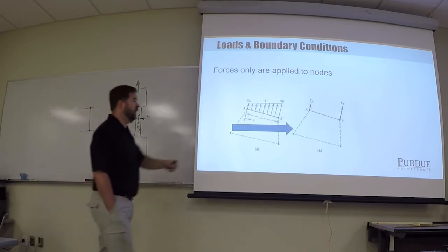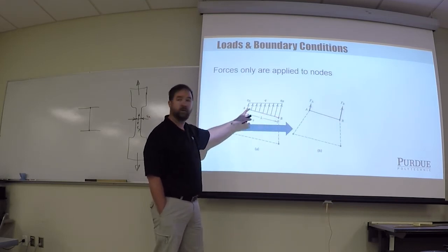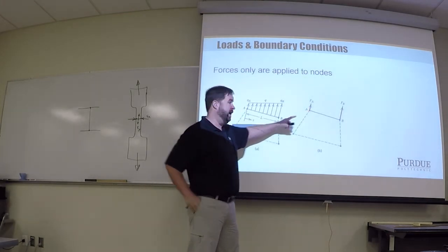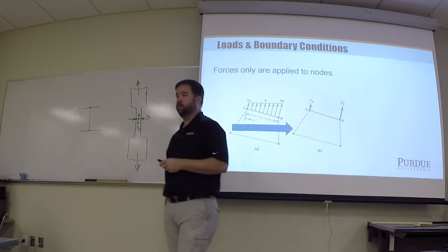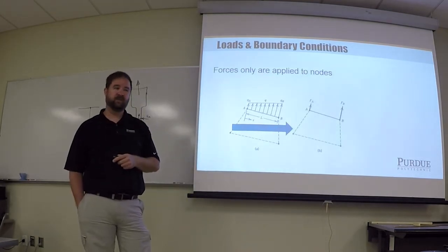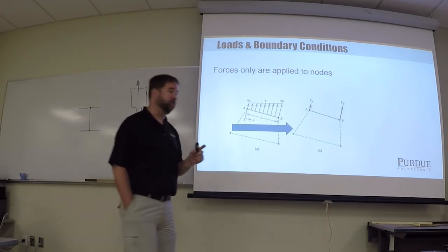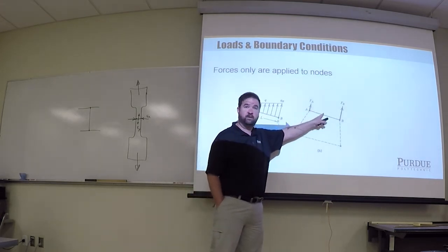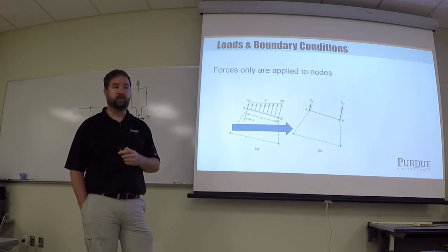So for example, if I have a distributed load along the edge of the element, the only places I can apply loads to anything in a finite element model is at the nodes. So I have to change my distributed load to concentrated loads at the particular nodes. Okay? This is a little bit of a theory thing again, because SolidWorks does this for you. But I want you to understand, as you're putting the loads in, kind of what it's doing. So if you tell SolidWorks that you have a distributed load, what it's going to do is take that distributed load, break it up into lots of little concentrated loads, and apply them at the appropriate nodes in your model.